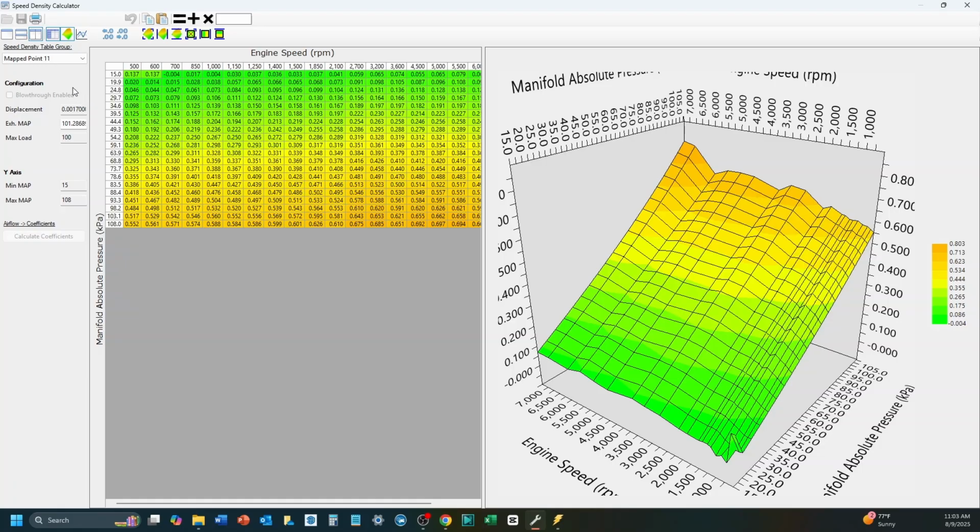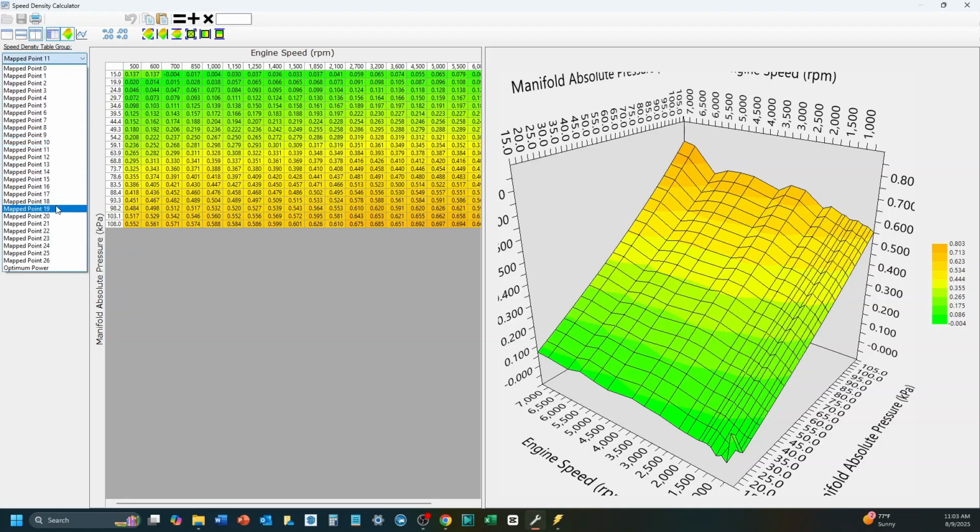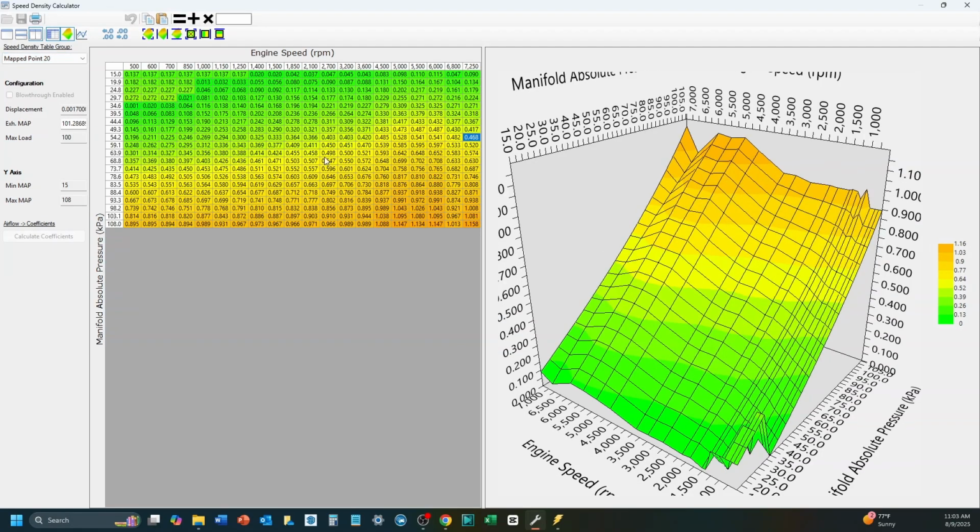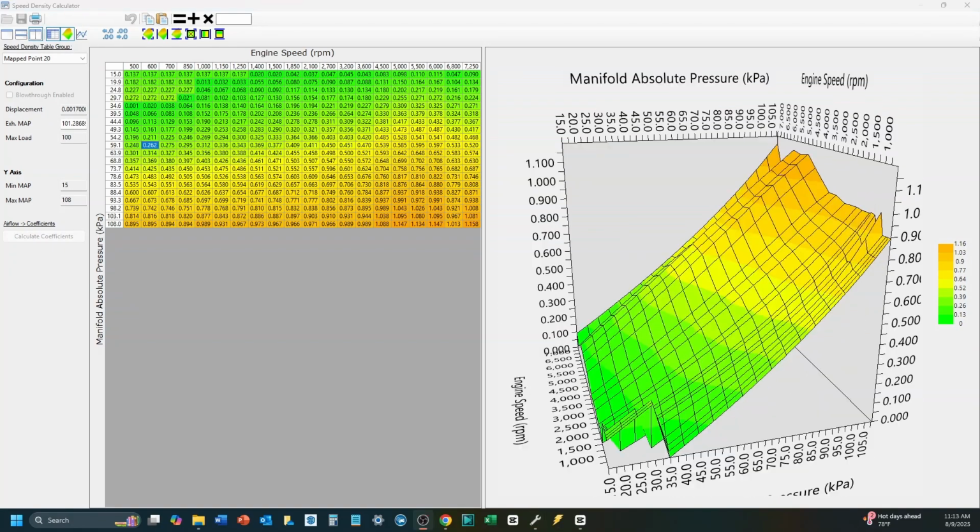Because if you are out cruising around and you're hitting partial throttle or full throttle and suddenly demanding a lot of power, the airflow model for these tables is absolutely vital, right, to get right. The other ones, you're going to want to tune them, right, but it doesn't spend as much time as it does in 10 and 11. And by inferring with the high-low method, it also spends a lot of time in 0 and 1. Optimal power, likewise, relies on table 20 quite a bit.